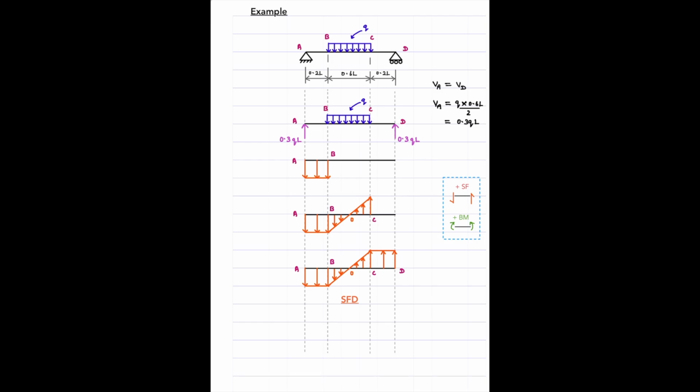So there is a one-to-one correspondence between the variation we have here and the loads acting on all portions such as AB, BC and CD. Fine. And also, when we consider the end D, we see a concentrated force acting here, right? Which is also acting upwards at this end. Any force acting upwards should be treated as a positive shear force, right? That's why we also finish upward here with that particular value 0.3 qL. Okay, so that's it for drawing the SFD.